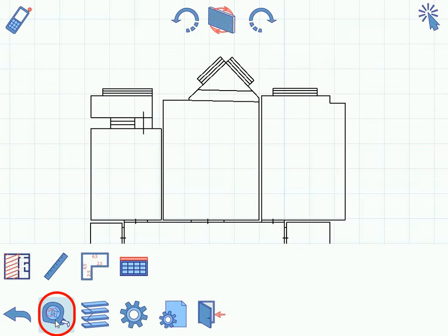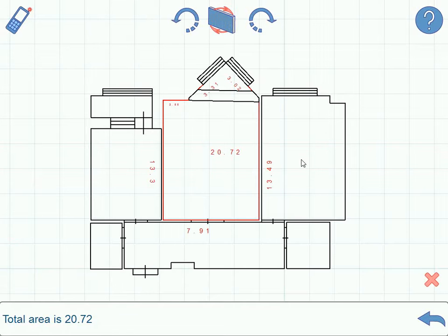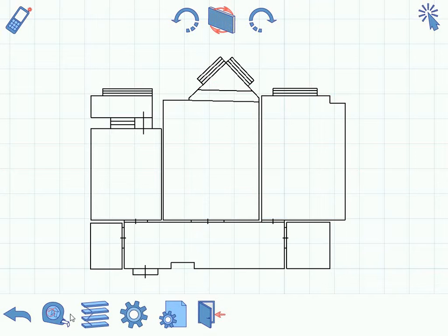The following section contains tools for numerical data. Square. This will show you the surface of a complete room, a selected part of a room, or of a group of rooms. Stairs, polygonal or rectangular objects stored on the floor will be subtracted from the surface when calculated. The surface of walls can also be displayed.